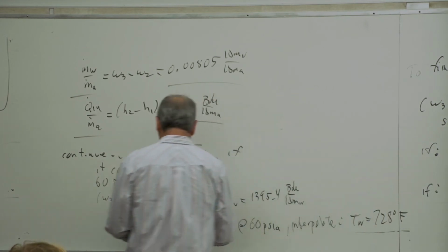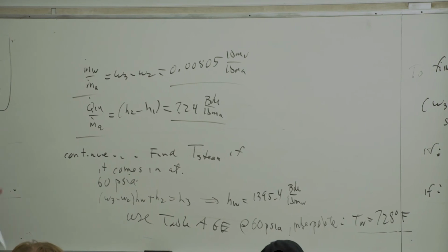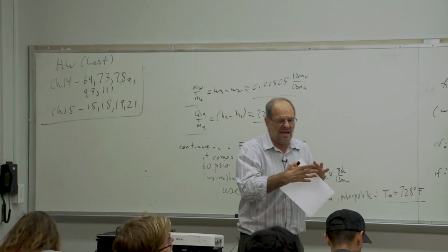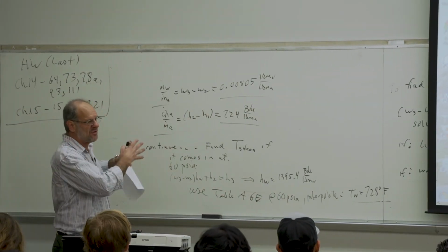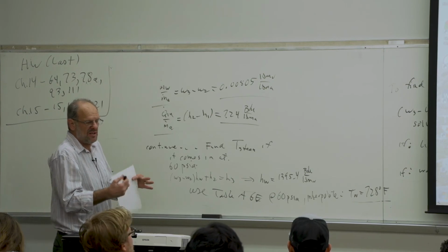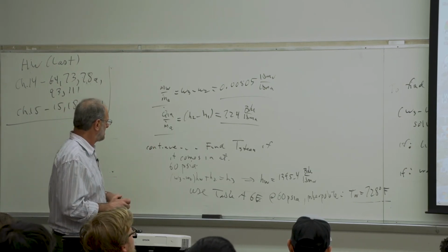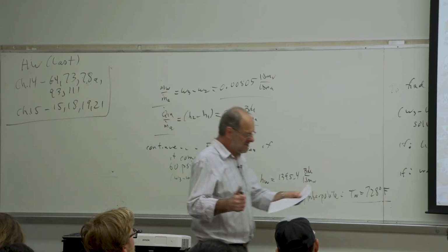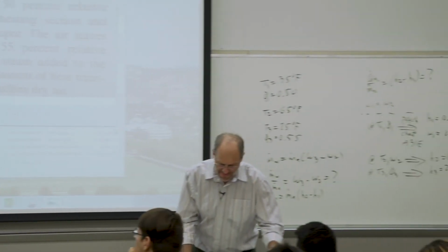Okay, so in this particular case, because it's superheated, you would use the superheat tables. Although when I was mentioning the general equations previously, I essentially implied that we could assume it was saturated. It just depends on the problem. So maybe I shouldn't have earlier said assume saturated. Just assume whatever is based on the problem statement. In this case, because we're given a pressure, it's superheated. So any questions on this particular example? Okay.